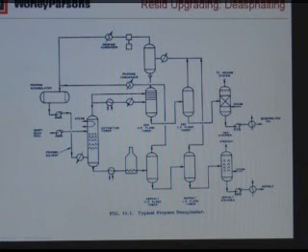And on the other side, you want to recover the solvent. Obviously, you need to recover the propane, and then you bring it back and reuse it. So it's simple in essence. Obviously, there's lots of pieces of equipment here. But basically, you have a solvent, you dissolve out the stuff that you want, and you leave behind this heavy asphaltene type material that you can make asphalt for roads out of. And then the other material, the deasphalted oil, you can use it as feed to other units, and it has some more value than the asphalt.